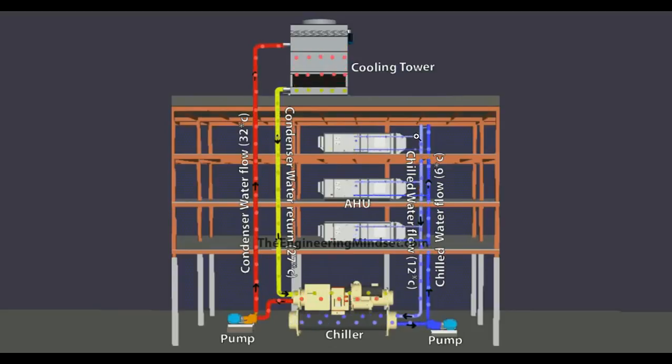This heat is then returned back to the chiller, returning here at about 12 degrees. By the time it leaves the chiller again, it will have given up 6 degrees Celsius worth of heat, so it's leaving at 6 again. So it leaves at 6, comes back at 12, and this cycle repeats and repeats.